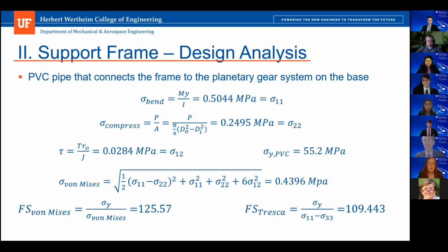The maximum stress on this section of pipe was found by considering the torsional strain from the motor responsible for azimuthal rotation, the bending stress due to drag force, and the compressive stress due to the weight of the frame, reflectors, and motors. The maximum moment on the pipe is the drag load on the frame multiplied by the length of the base subsystem.